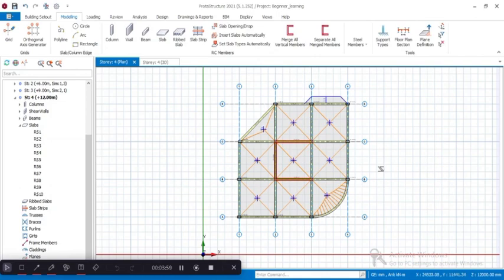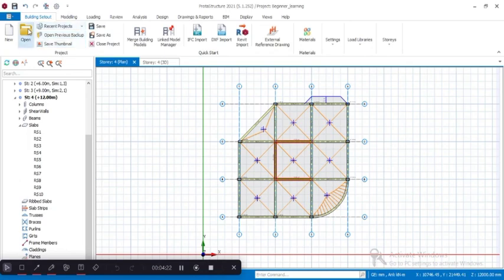Wall loads library, inserting brick wall loads. So this is, let me say, the partition walls. So you can set up predefined wall loads and then apply them using a drop down list when adding the wall loads. So go to building setup and partition walls, load libraries.